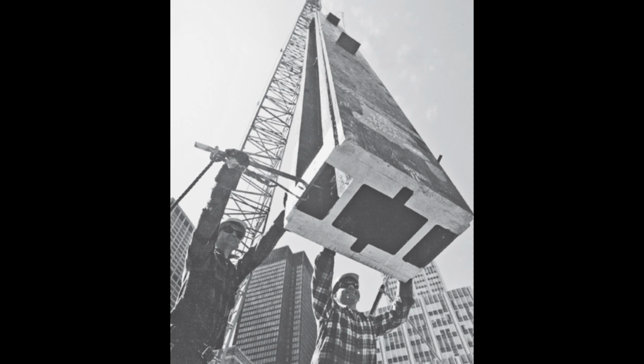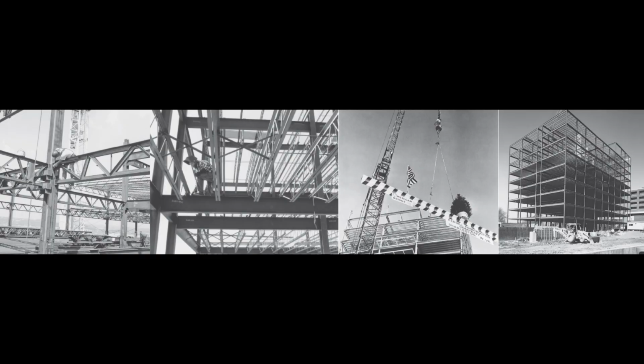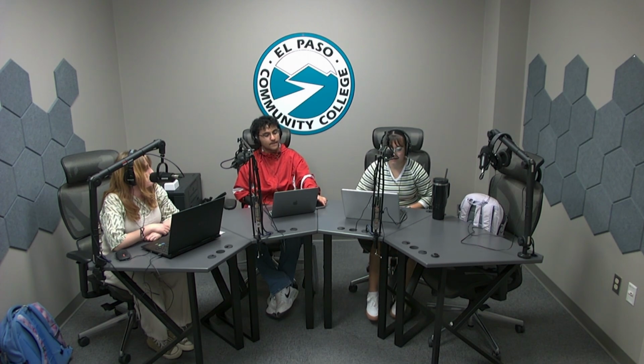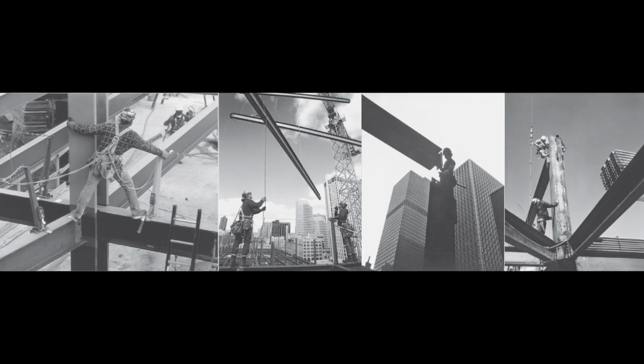They also talk about erecting the upper tiers, which comes after erecting the first tier, which is after the 2-story column section, and they are hoisted into position and connected by splice plates on top of the first tier of the column, extending above the working platform.